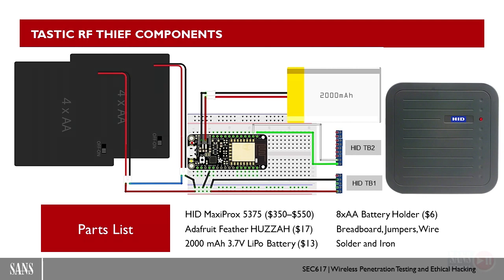With this, we're doing 12 volts. With the ones that I've done, adding more batteries in a smaller format than the AA's, we get up to 22 volts, and we can get significantly larger read range. We've got average read range in free space of about 5 feet. That's better than the 1.5 feet, 2 feet, 3 feet with the AA's. Okay. The other design decision that I made was to have one set of batteries. We do some voltage step down from the 22 volts to 5 volts to power the Node MCU or the Adafruit Feather. So we have one set of batteries to worry about.